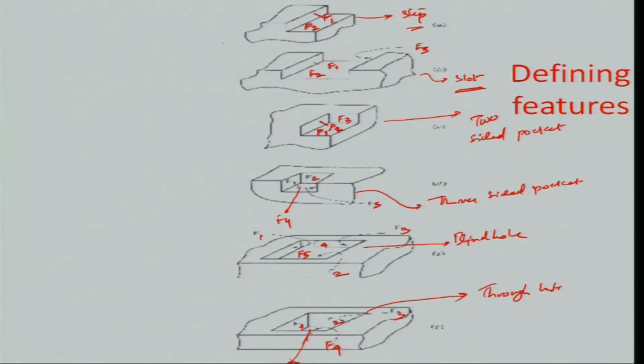So let us now do an adjacency graph model for these parts and try to understand how the part geometry goes. You have 2 nodes here corresponding to the faces F1 and F2, and there is one interconnect between the 2 faces which is of a concave type, and remember that the attribute added to the concavity in the earlier expression was t equal to 0. So you can call this the graph model for the solid which represents the step. Now it is a part of the database, you have stored it.